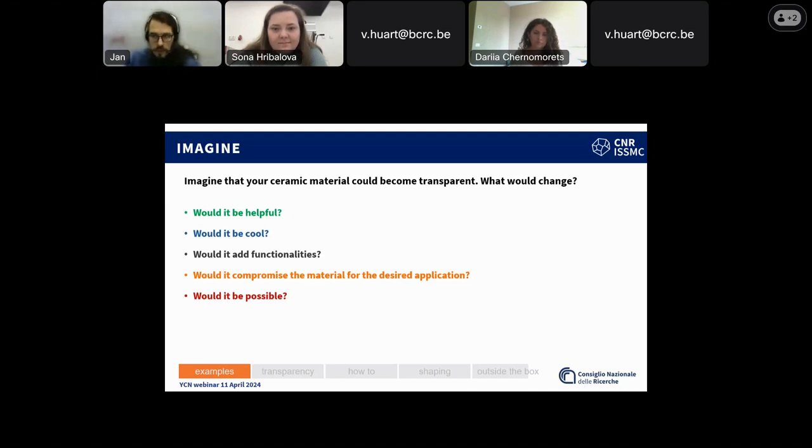For this, actually, it was really Coble's work that was pioneering and enlightening at the beginning, because what he did was he was very cunning in using the right sintering aid and the right sintering conditions, of course. But the main point is you need to avoid trapping pores inside your grains.